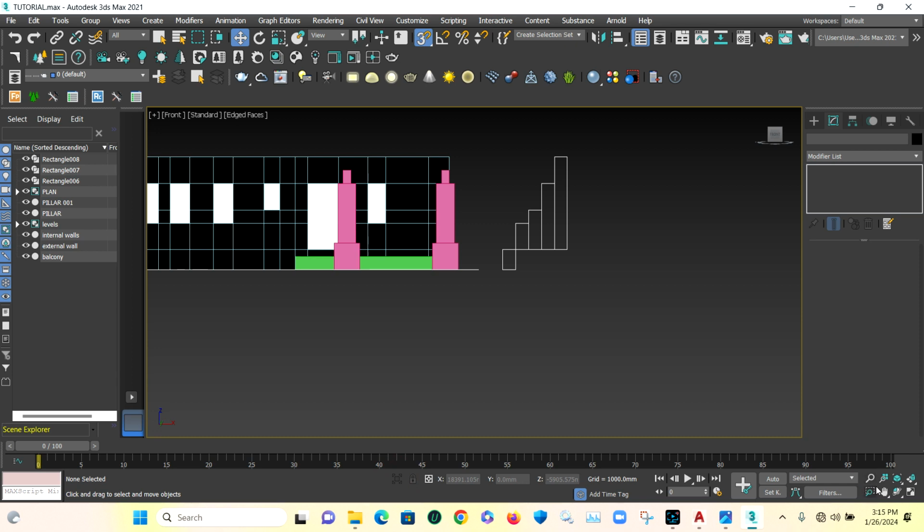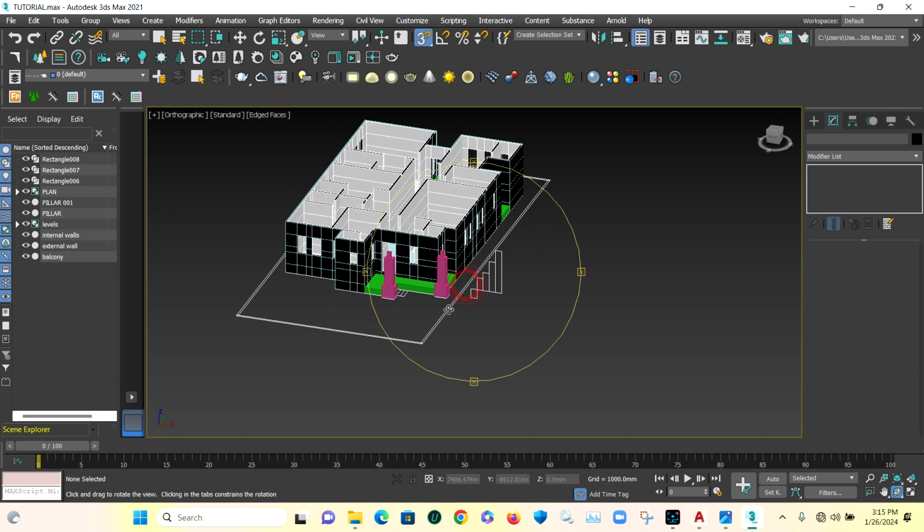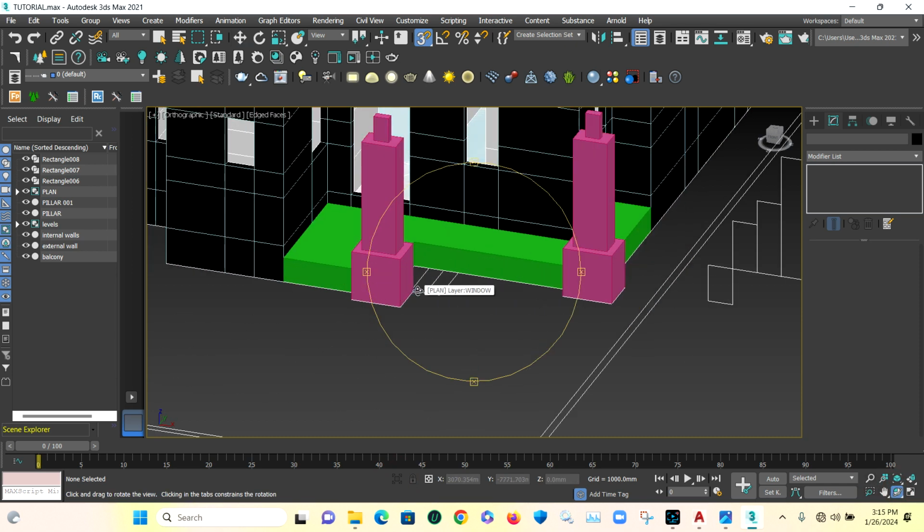This is 500, and then we have 3 steps, and we want to achieve 500 with 3 steps. How do you go about it? Now you can choose to go with 150, which is the standard height, that is 6 inches. If we go with the first 150, that means at the second step we're already at the height of 300. Then at the third step we're at the height of 450. Then you have that more 50 to climb if you choose to.